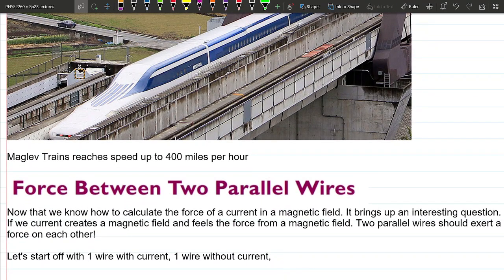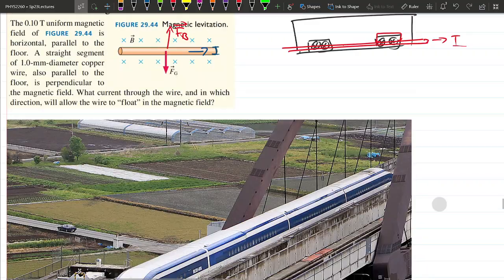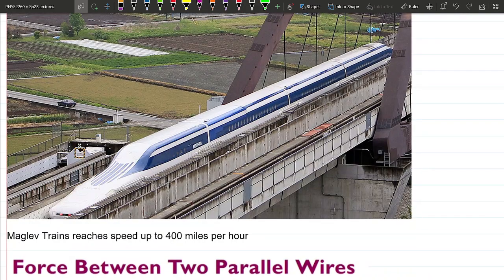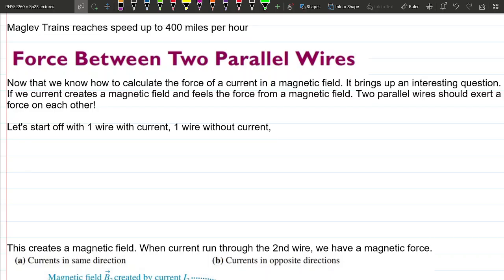But there's also physical brakes, just in case there's an emergency stop. They just use metal-to-metal braking, right? Yeah. But this type of magnetic braking is nice because you actually recover the energy from the kinetic energy of the train. So we'll get to see that next time. Come back after spring break.